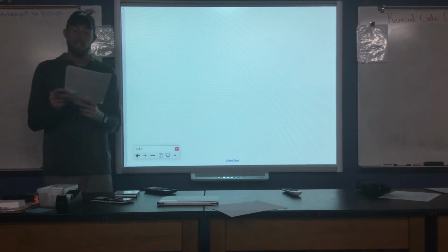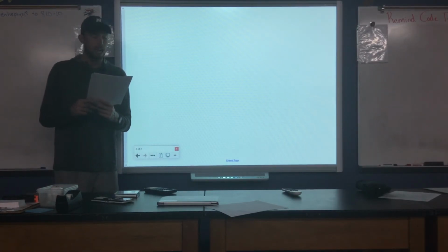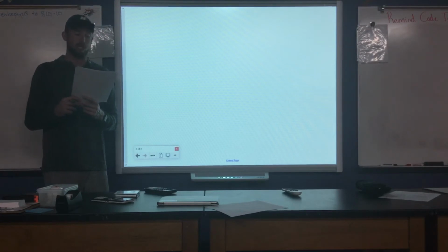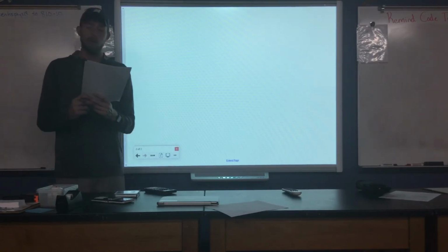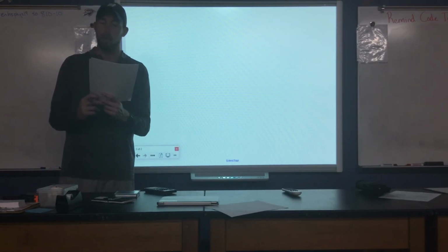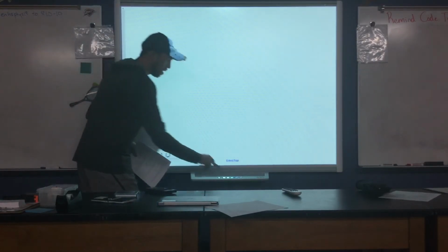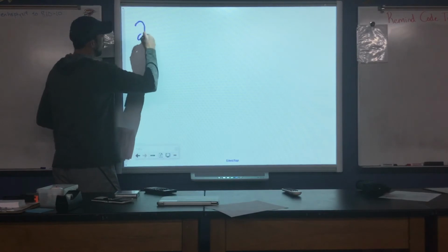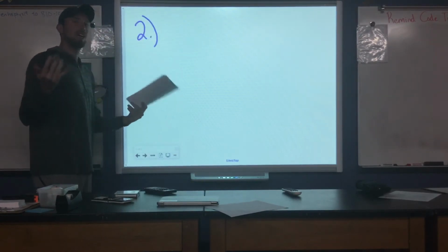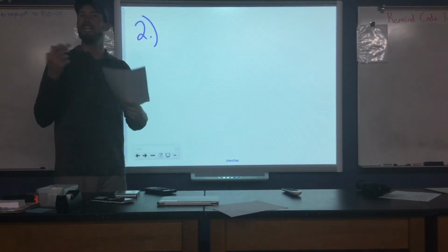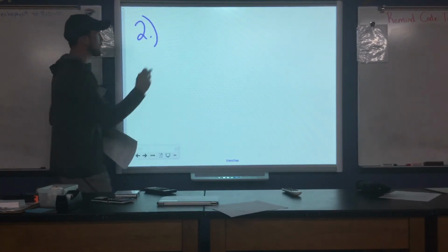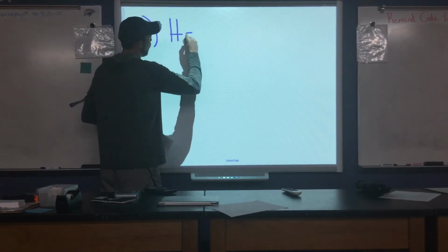The temperature on the outside of the window is 5 degrees Celsius, and the interior temperature is 30 degrees Celsius. Assuming the window is a square with dimensions of 2 meters by 1.5 meter, determine the thickness of the window in centimeters. So here we're looking at question number 2. And then the same idea using our heat transfer rate equation, but now we're trying to find a different variable, the thickness.